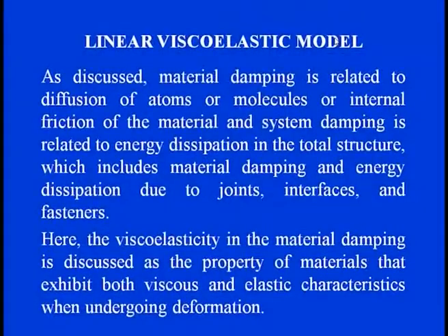The viscoelastic property in material damping is the property of a material which exhibits both viscous and elastic character when it is undergoing certain deformations. That is how the kinetic and strain energy arise, because localized deformations are there. Because of this energy transformation, the molecules under load or stress are deformed, strains are formed because of this deformation, and the energy is taken out from the source.